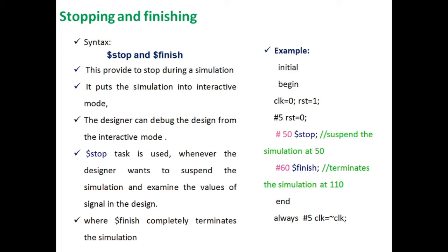Okay, that means the $stop task is used whenever the hardware designer wants to suspend the simulation. I'm not completely terminating it, I'm just putting it on hold for some time. So he can examine the values of signals in the design. That means for the corresponding input, I can examine what the corresponding output is. That is the usage of